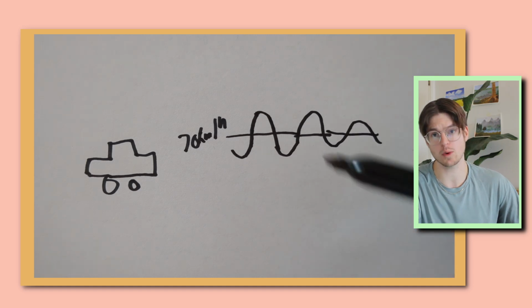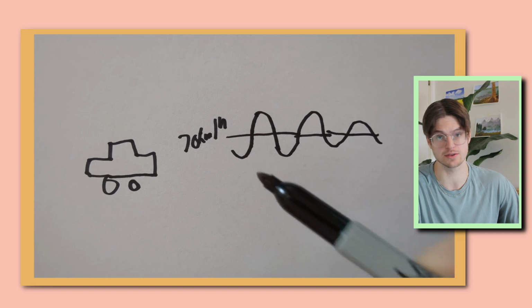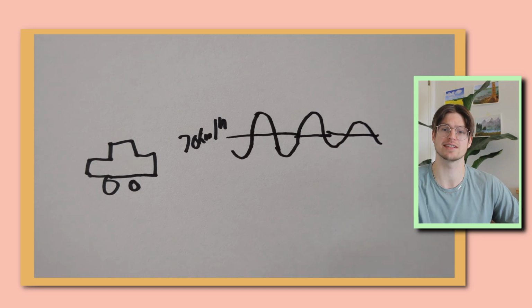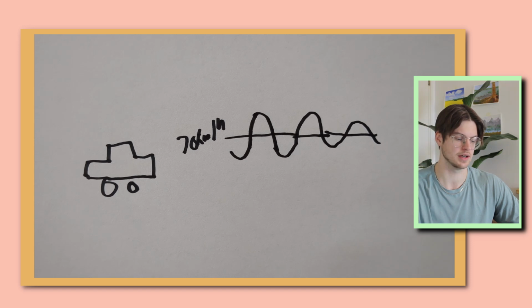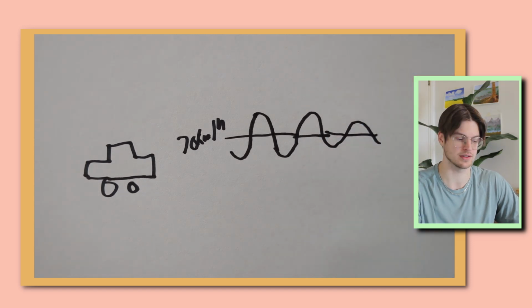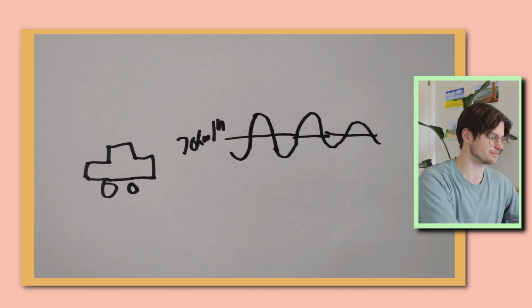This is a way to drive a car for sure. You will be around 70 kilometers per hour, but it's not very smooth, and I don't think you would like it. And for many processes, it is not very optimal either. And this is kind of what the PID regulator solves, right? Specifically the P part of the PID regulator.